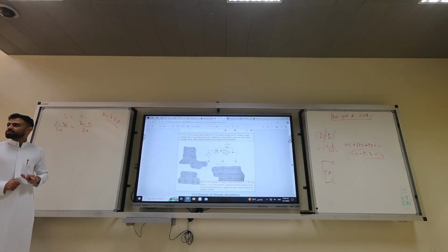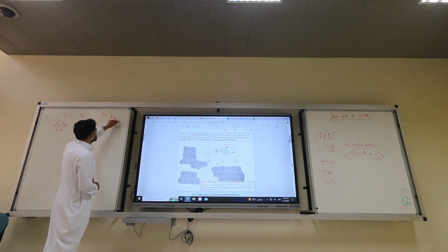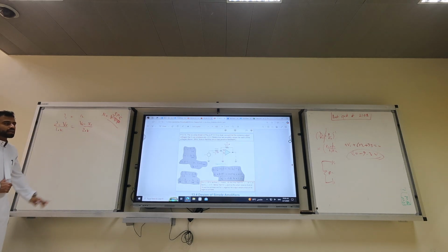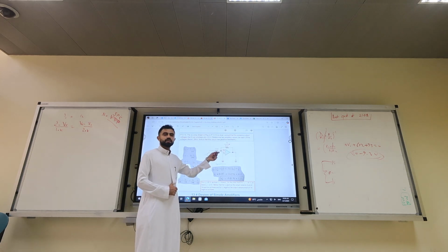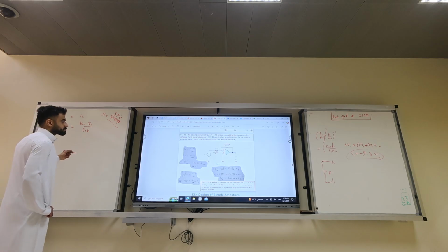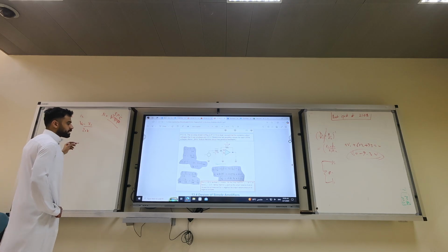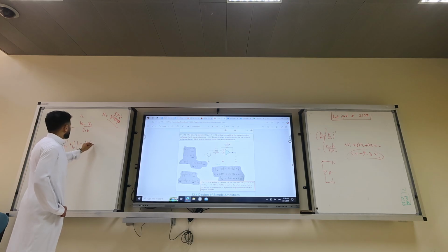Was it virtual? No. Summing point constraint, SPC. We don't have SPC here, because it's a positive feedback, not negative. When you solve it, you will have Vx times 1 over 20 plus 1 over 10 equals V output times 1 over 20 plus 1 over 5.